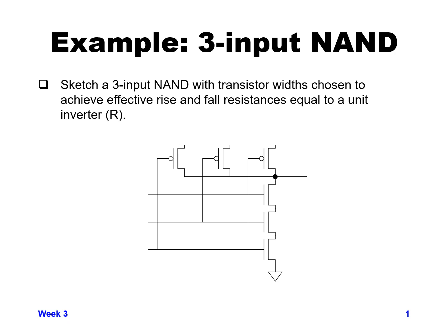That way the 3 in series would have a resistance that would be, since the wider device has smaller resistance, a size of 3 would give us a resistance of R/3, and 3 of them in series with each other would be a total resistance of R. For PMOS, the previous size for an inverter was a size of 2 for the PMOS.